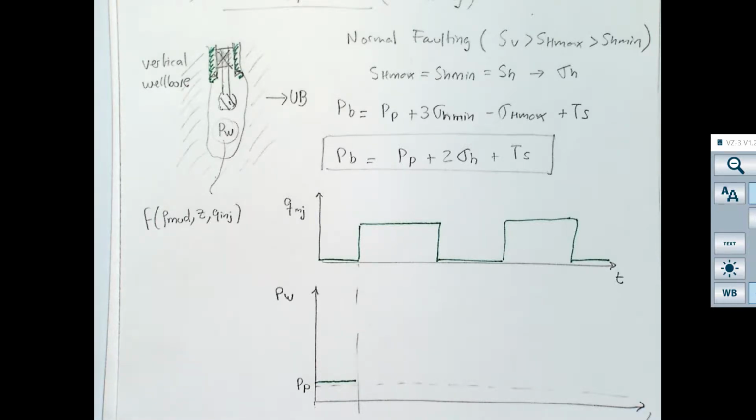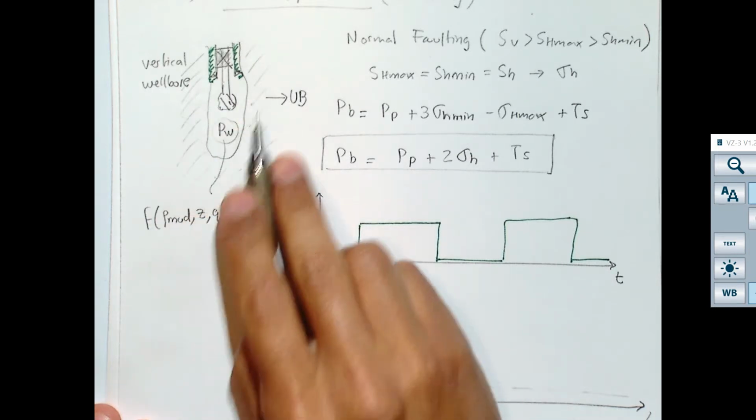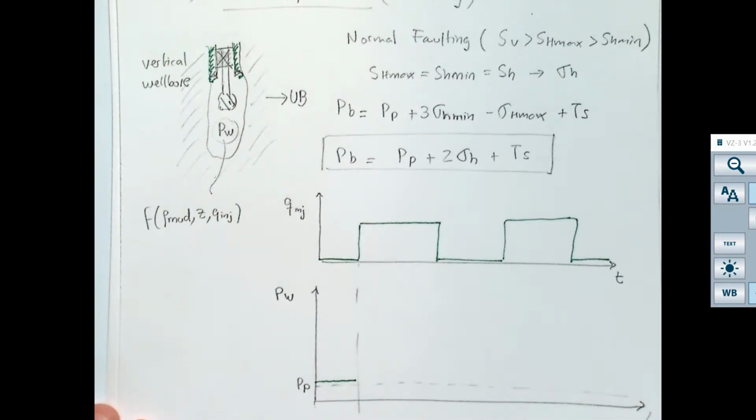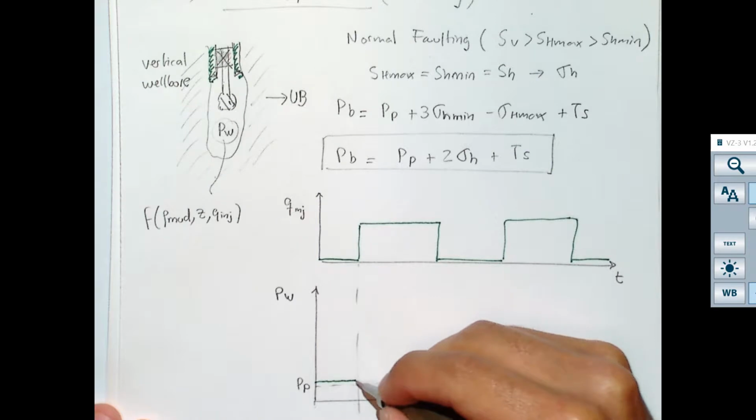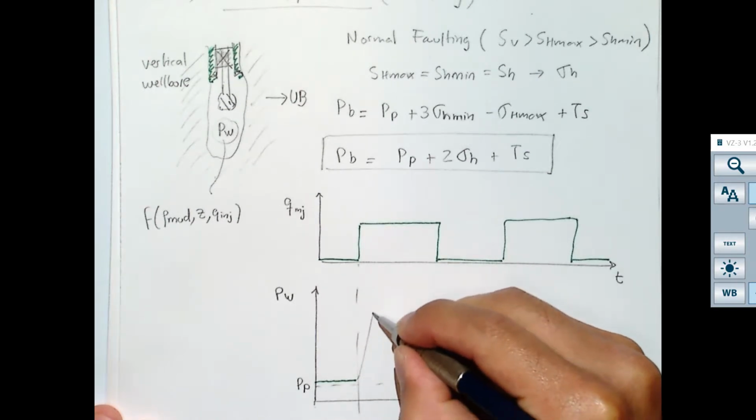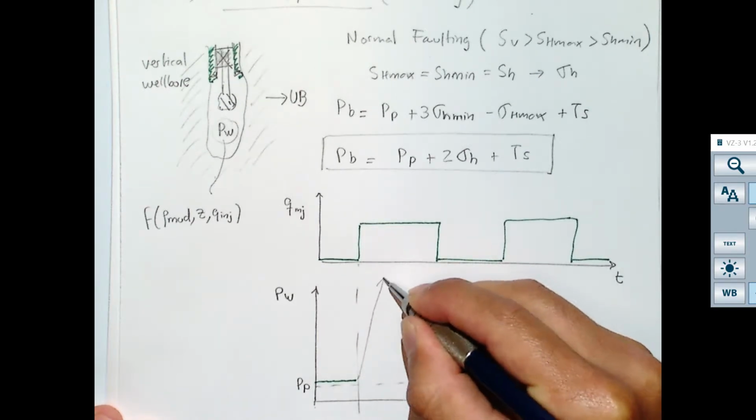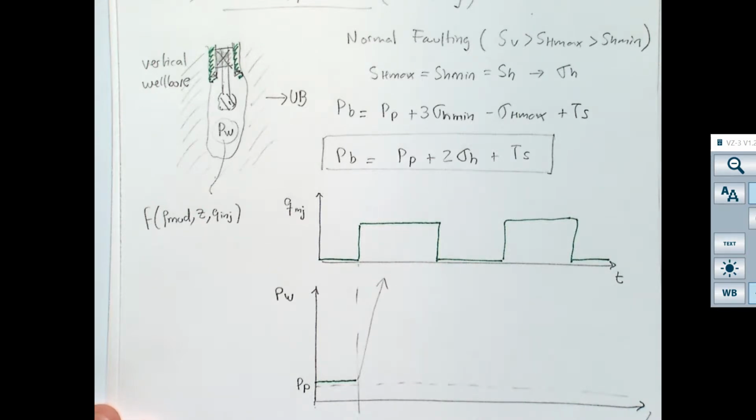Okay, so if I start injecting, and this is more or less a closed volume, what's going to happen with the pressure? It will go up, right? So I agree with that. It will go up. But now my question is, will it go up forever? Can it go infinitely high? No. And what is going to be the maximum value of the pressure that you can get to? It's going to be PB, breakdown pressure, and I heard something else?